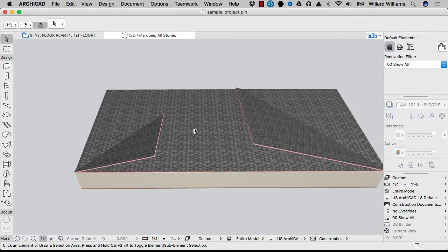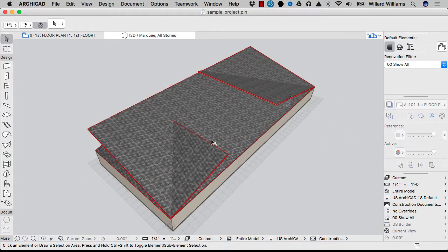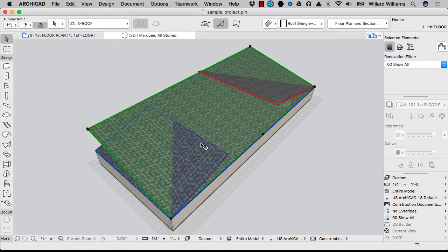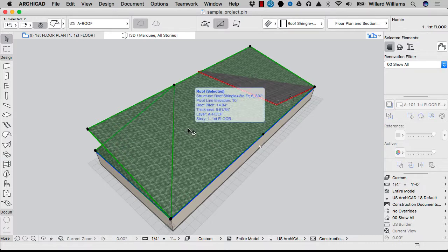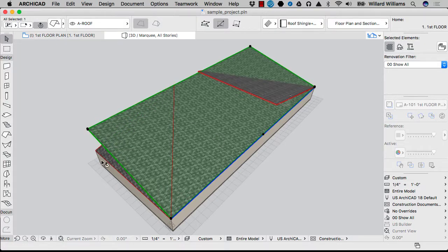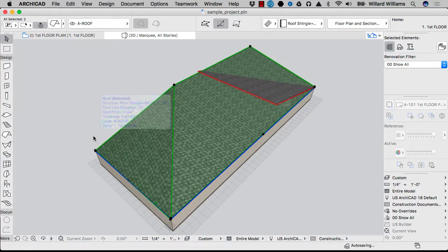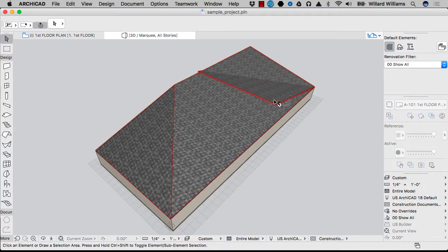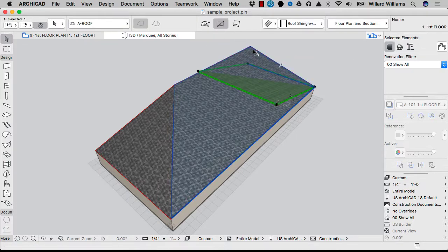And what I'm going to show you here is, if, say, this is kind of the direction you're going with your design, what I'll do is I'll select one roof, I'll select the other roof, and that first roof that I selected, I can use the command button or control button, and I can trim that edge to that roof. Now if I go back and I select this roof first and this roof second, and I can cut this one. So now I've cut this edge exactly to that edge piece. So again, first roof, second roof, control or command, and I can cut that roof.